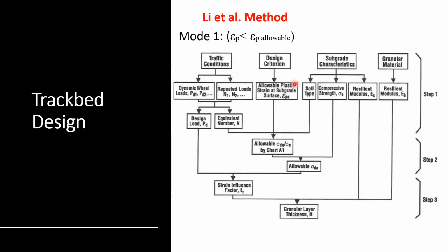Subgrade characteristics, we talked about this: soil type, your compressive strength. That's when your geotechnical sense kicks in, and you have to pick a number that you feel comfortable to load your soil to. Resilient modulus, one of the challenging parameters. There is a lot in the literature about the best way to simulate the resilient modulus. I haven't seen resilient modulus testing being done specifically. I guess part of it is it's very research oriented. So unfortunately, in practice, people tend to get the resilient modulus from some other parameters.